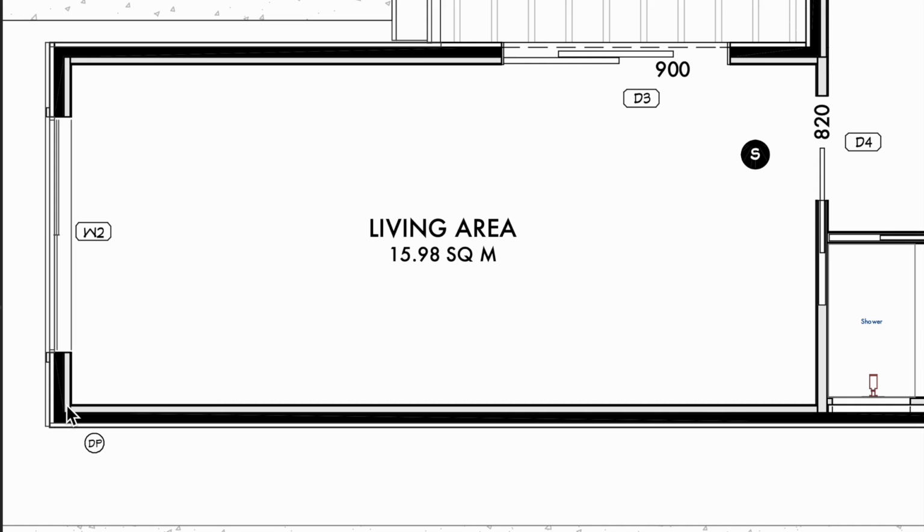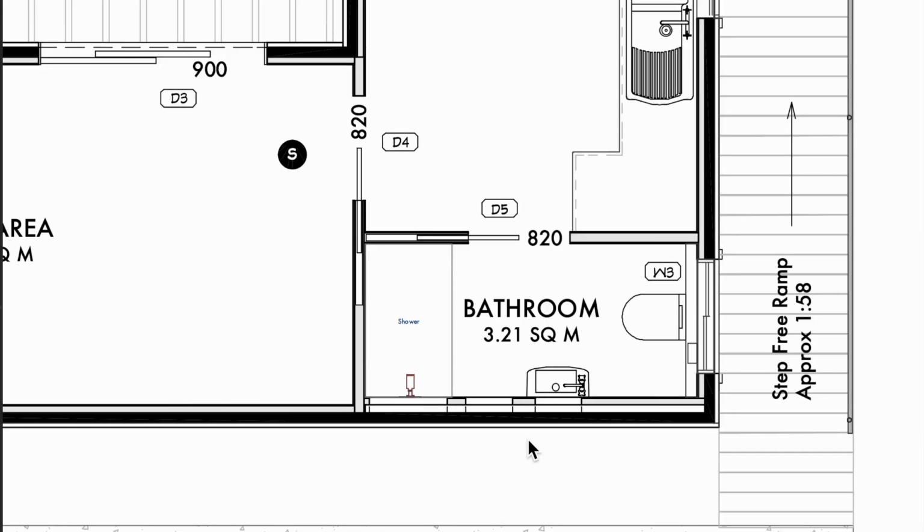So that's where you can add that offset. This length here on the outside of cladding is going to be offset on the left by whatever the thickness is of your material versus what you were measuring on the inside floor, the clear floor area. That was the point of doing that, so it could give you a couple of values rather than you having to do a separate calculation if you've got, say, 1, 2, 3 materials to be quoted.